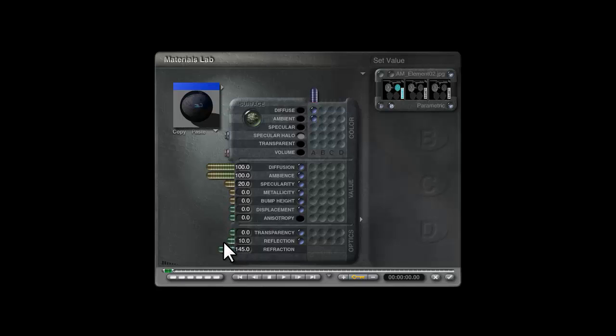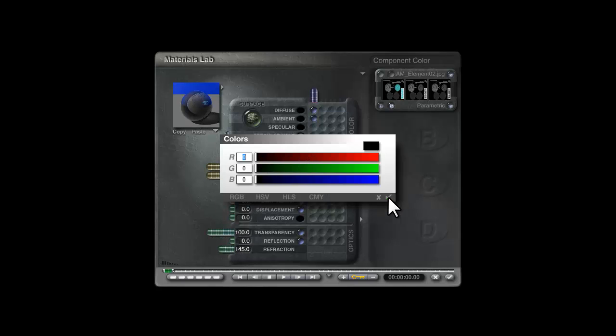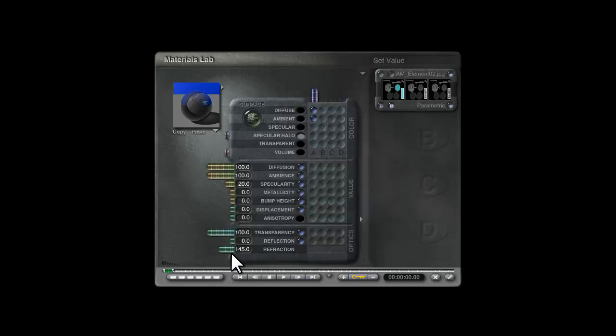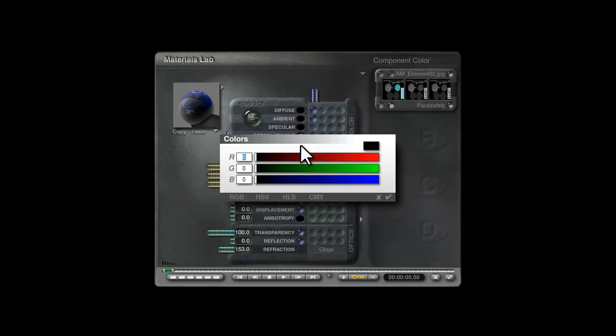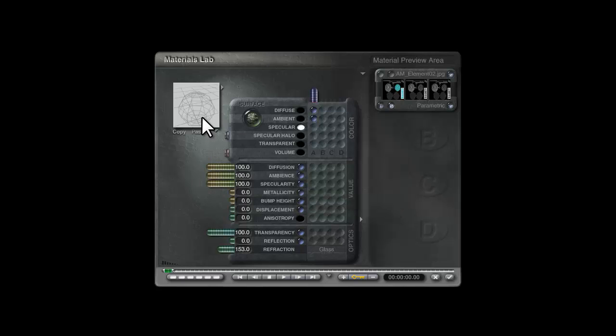that's quite high. We could get rid of the reflection and use transparency and make sure that this was set to fully black, so it's not actually transparent. I'm just getting the grazing angle reflection. Make that like glass 153. Okay, that's set it up there. It might benefit from specular, but it won't do anything if we've got no specular highlights, so I'll give some specular colour and then set the specular halo down so that it gives me a nice sharp highlight there. So that's made it glow and have a glassy surface.